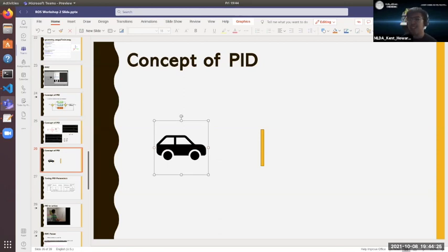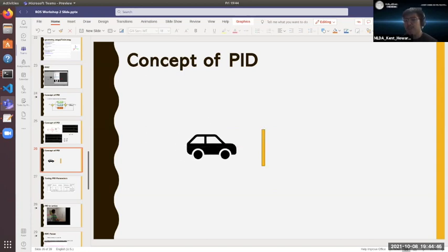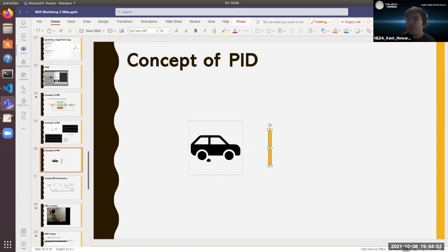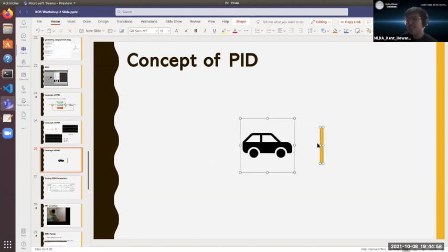And for the last example, the integral controller, why do you use a PI controller? Imagine we have the car and we have a certain amount of error. And this pole, similar to the car, is also moving at a certain constant speed. Then at one point, there will be a value of distance that corresponds to the same speed as the pole. What will happen is the pole will keep moving and the car will have a steady state error. It cannot catch up with the pole. It will just have that gap, but it does not fall behind the pole either.